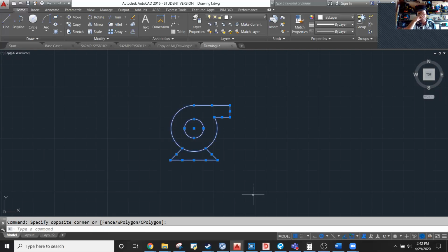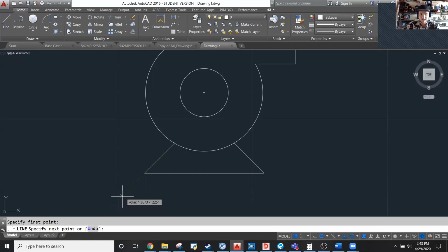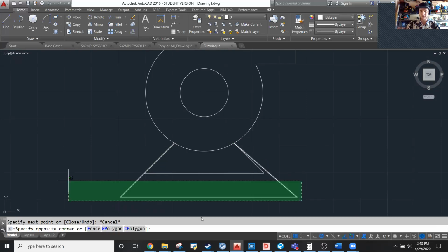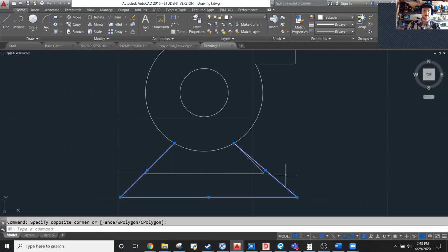So you'll notice in here, a lot of these operations I'm doing, I'm drawing half of it and then mirroring. The reason for that is when you're drawing angles and stuff, it's much easier to just draw the half you want and then copy it than it is to draw that line on the angle and stick it here and then exactly mirror it on the other side, because you need to know exactly what length that bottom edge is. And if you don't hit that precisely by eyeballing it, then your angles are off and this thing looks all janky. So it's much easier to just draw half of it and then mirror it.